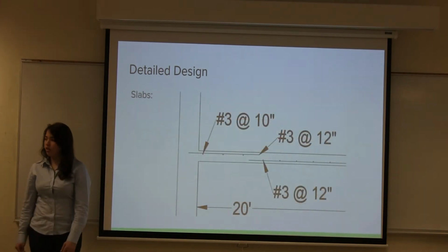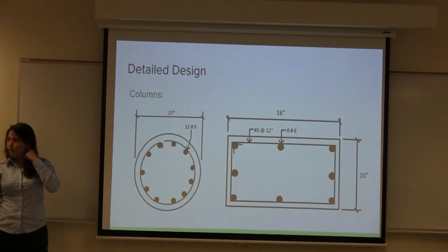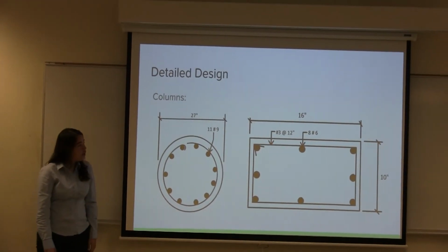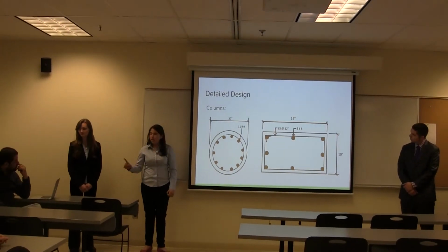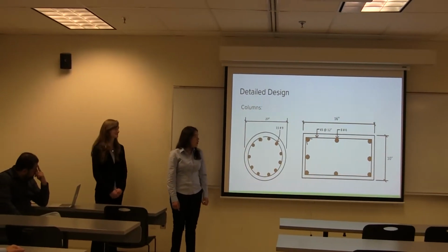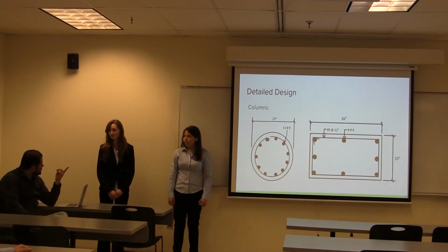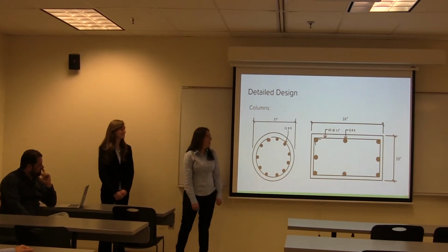So this, where you get this, go back. So this detailing is wrong for the spiral. This spiral reinforced, the circular column, has to be a continuous spiral over there. Yeah, it is, it's just... Where did you get this, did you draw this? Yeah, okay. Full circle, okay?